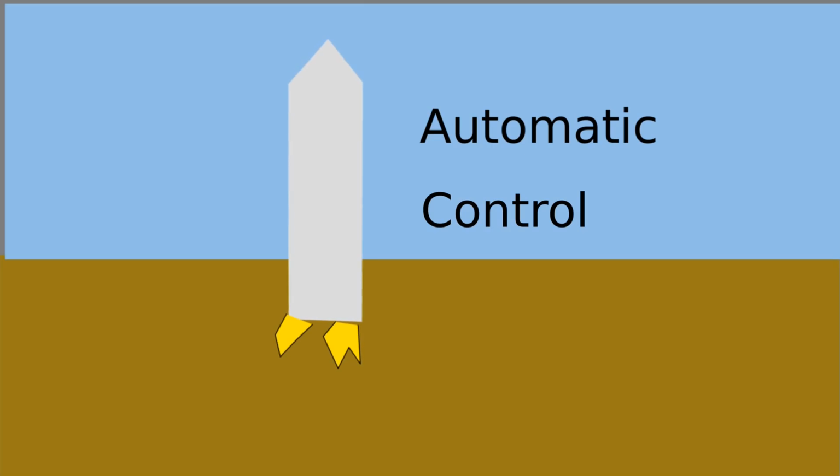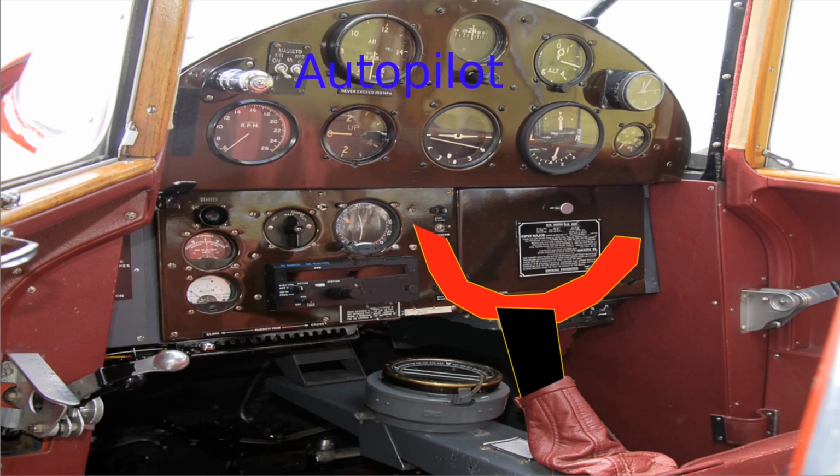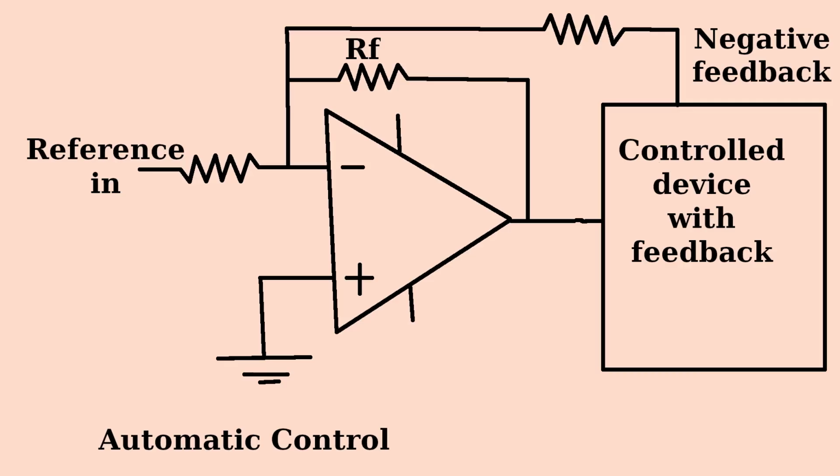Automatic control of servo motors and other systems is basic to most technology. The summing amp is the most basic form of controller. Two inputs are needed, a reference and a negative feedback. Voltage on the reference is summed with the negative feedback voltage, and the two subtract. When the two are equal, the amplifier output is 0. If anything changes, the amplifier drives things until the sum is again near 0.